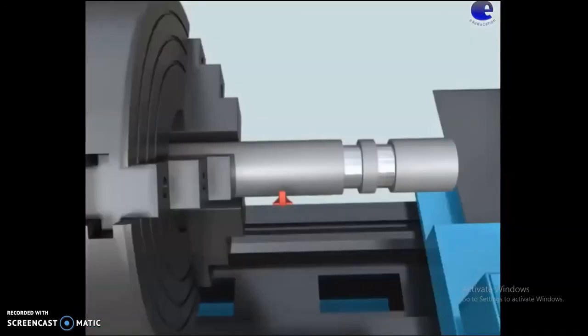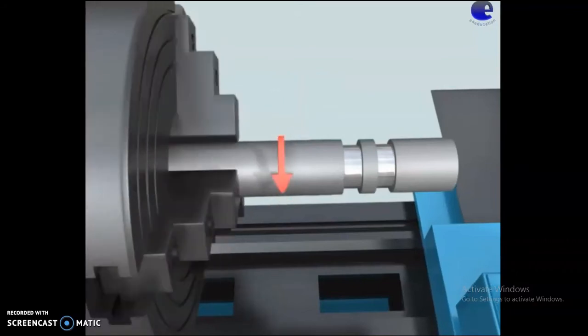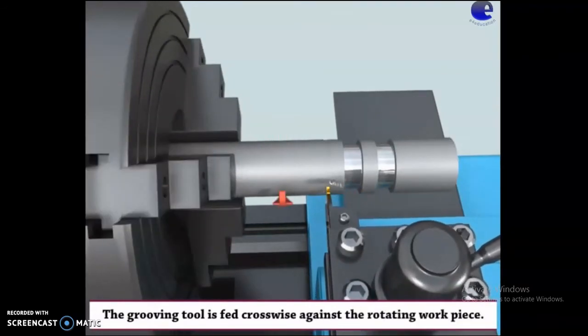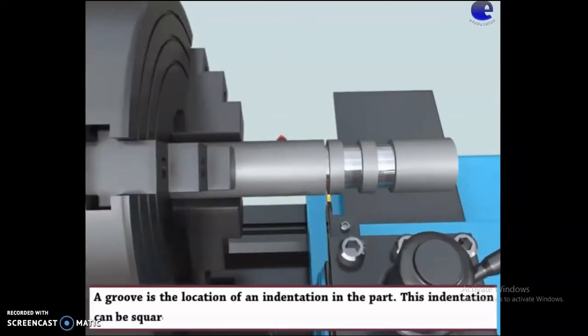Next is the grooving operation. It is also known as recessing, undercutting or necking. This is a workpiece. It is rotated. The grooving tool is fed crosswise against the rotating workpiece. A groove is the location of the indentation in the part.